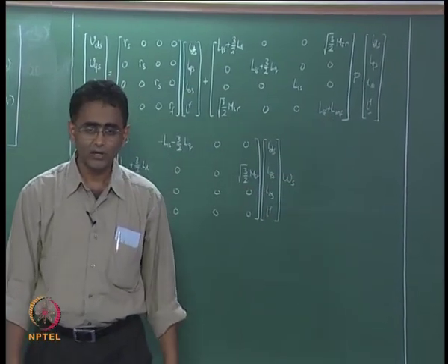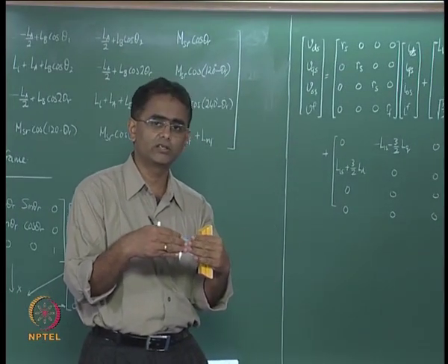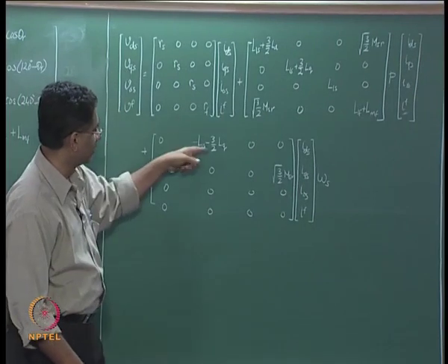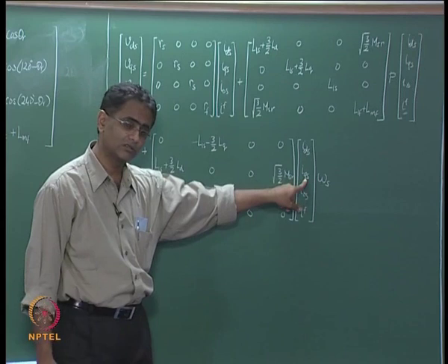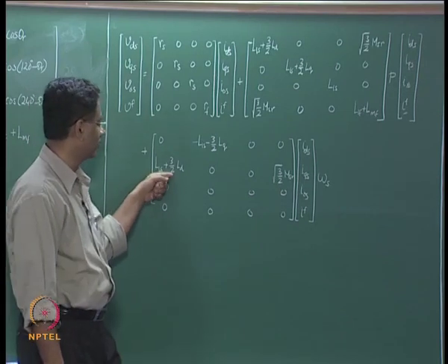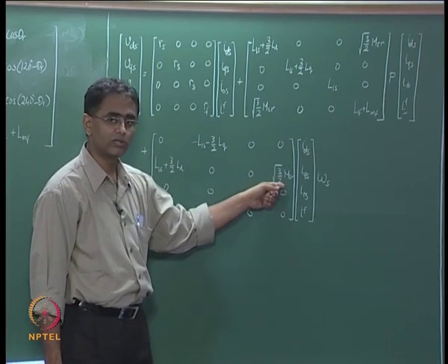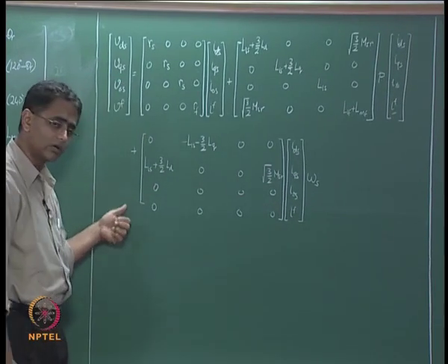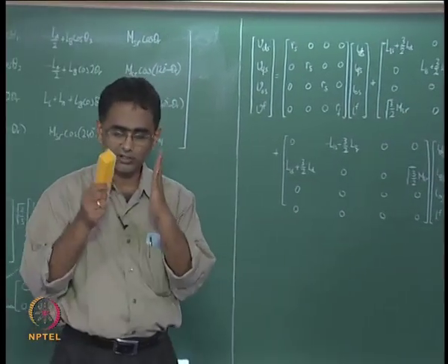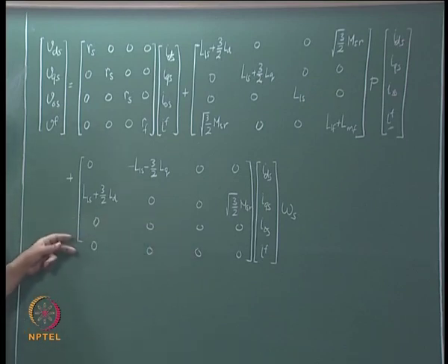We noted earlier that the speed EMF terms arise on a particular axis due to the excitation on the 90-degree axis, and therefore if you look at the d axis equation, you get a speed EMF term due to current flowing on the q axis of the stator. On the q axis you would have speed EMF terms due to currents flowing on the d axis. So you have one stator d axis fictitious winding, and the field also is on the d axis. On the rotor there are no speed EMF terms because the rotor coil is not a fictitious one. It is already there on the d axis only, it is not being transformed to something else, and therefore there are no speed EMF terms here.